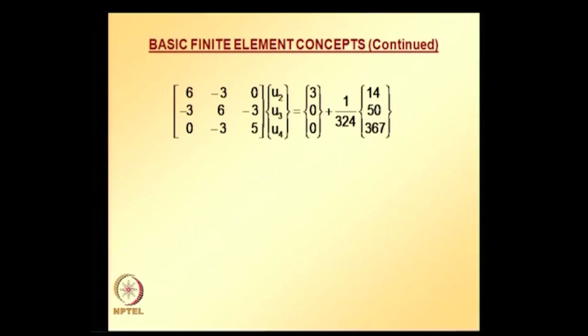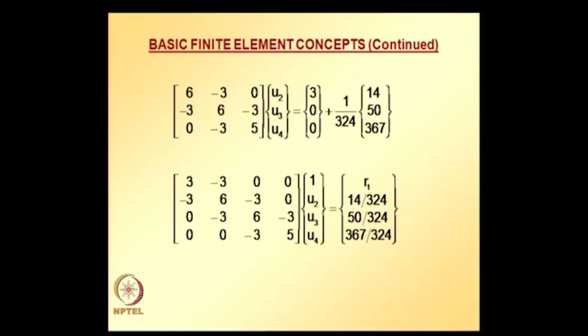And now if you see the left hand side, you have all the numerical values, so you can easily find the value of that vector, and once you get the values of that vector, you can solve for u2, u3, u4 by using any of the numerical techniques like the Gauss elimination method. So, the other way, I mentioned to you, there are two ways. One is you can either remove the rows and corresponding components in the force like vector. The other way is based on simple reasoning.